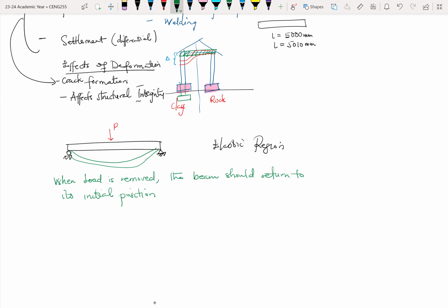Okay. So I think last semester when we were looking at engineering materials, we looked at the stress-strain curve for steel or so, where we mentioned that if this is your strain, this is your stress, your plot could go, so you could have some linear variation, have a curve, go all the way up, and have something like this. All right. So this region here is what we call the elastic region, where deformation is recoverable.